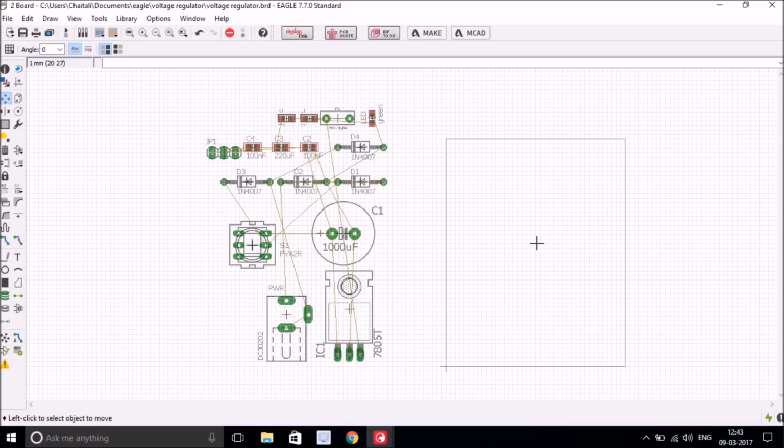First of all, you can see there are a couple of yellow wires called air wires. They're connected to each and every component that we have in our schematic sheet, and these air wires basically give us the direction of how the components are connected to each other. We will talk about this later on, but first let's put the components onto the board.